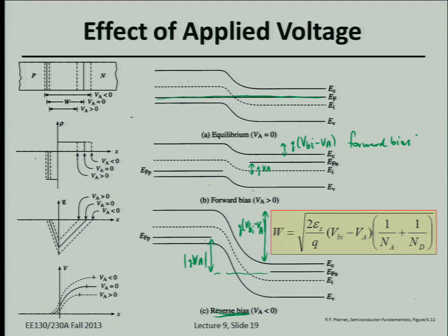Okay, so if you look at the energy band diagrams, what's one easy way to tell if we're looking at a diode, first of all, in equilibrium? That's really easy, right? Fermi level, very good. And then if the Fermi levels on the left and right side, oh, I forgot to point out, now we're starting to use this notation, E sub F sub P. That's the Fermi level in the neutral region on the P side. E sub F sub N is the quasi-Fermi, it's not the quasi, sorry. It is the Fermi level in the neutral region on the N side. So that's different from the quasi-Fermi levels. That's why I'm getting confused. So that's just a little bit of new notation.